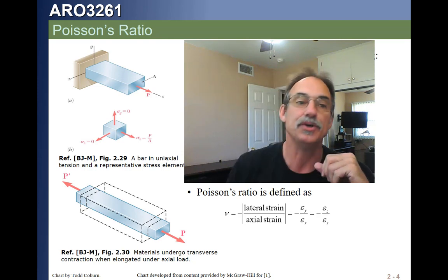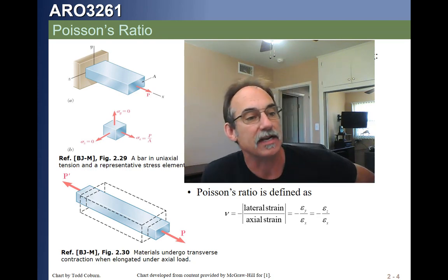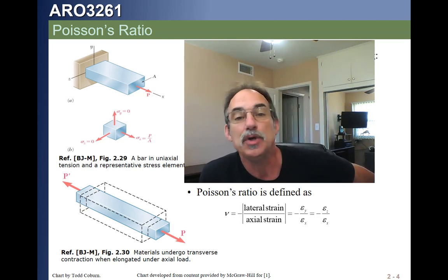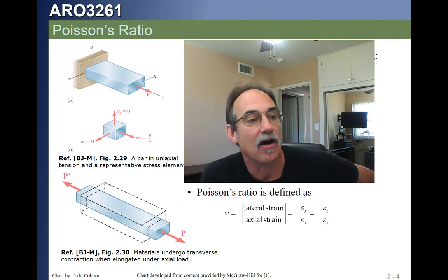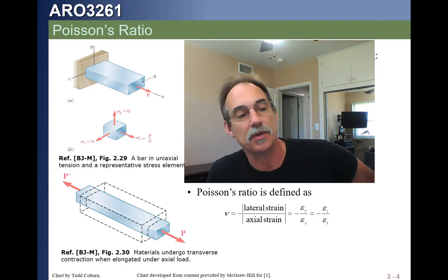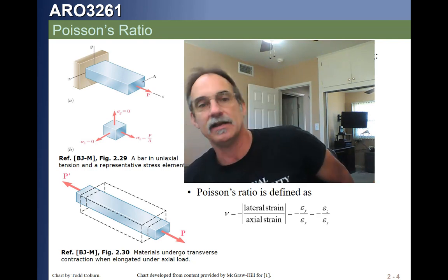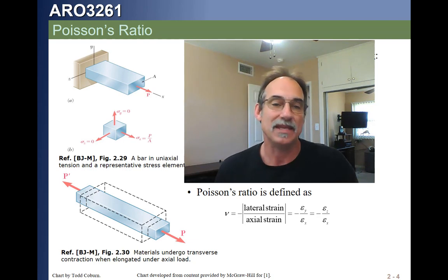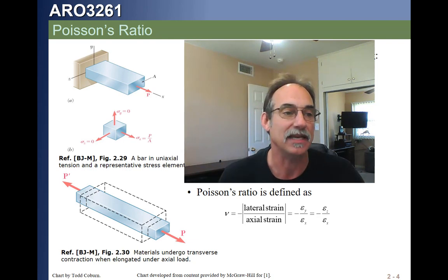This brings us to Poisson's ratio, which we're going to define. We've got a nu here. The Greek character nu is often used. Also, you'll see in our handbook, it's called mu. So mu and nu are both commonly used for Poisson's ratio. This nu is more common. The reason I use mu in the appendix is because that's what's in MMPDS.